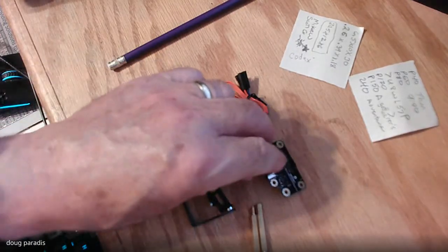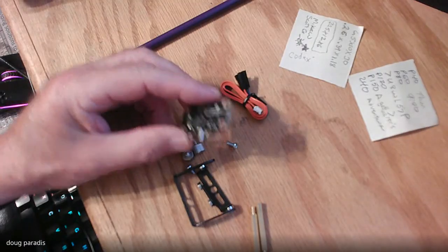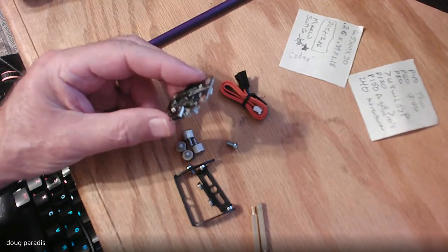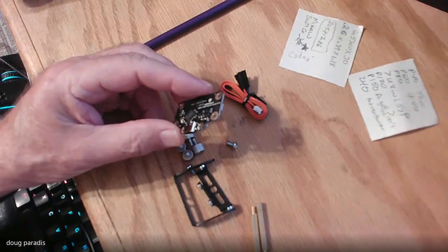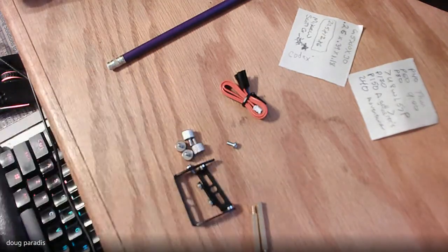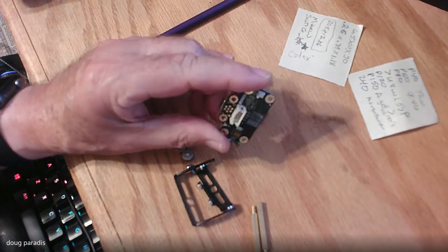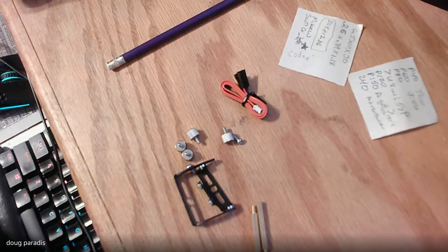Otherwise, let me put it this way. If you're using this just to see if it works on your computer, it's easier to just plug the USB in. But if you're doing it with a microcontroller on a robot, then you want to use the I2C bus, which is on this side. Yeah, so having 4 pins probably supplies power too. Yeah, it supplies. Well, is that one of the Grove connectors, Doug?